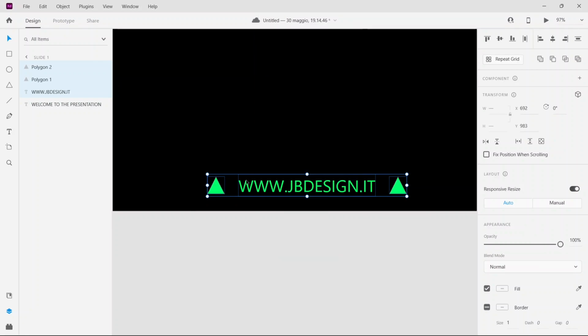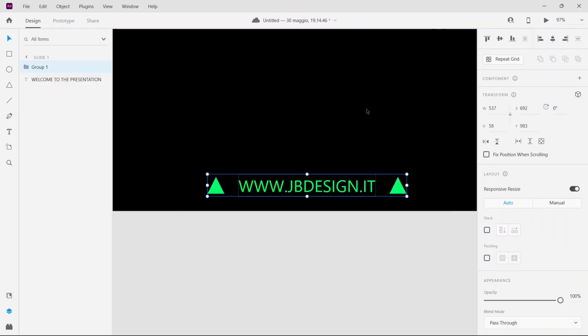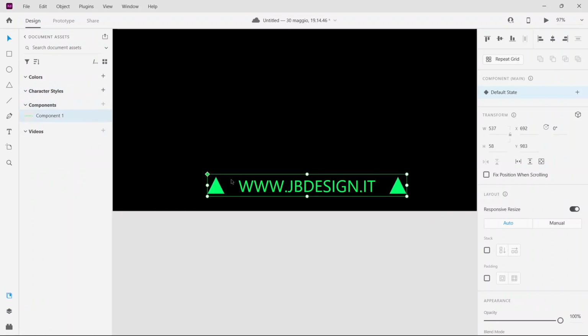So we can click onto the elements, we can select them, and then we can click with the right side of our mouse and then click on Group. Now we have our group, and we can go to the Assets and click on Components. So we have now an instance, we can see the green border, and of course, if we change this first instance, all of its copies will change, because as we saw in one of the previous videos, they remain connected.